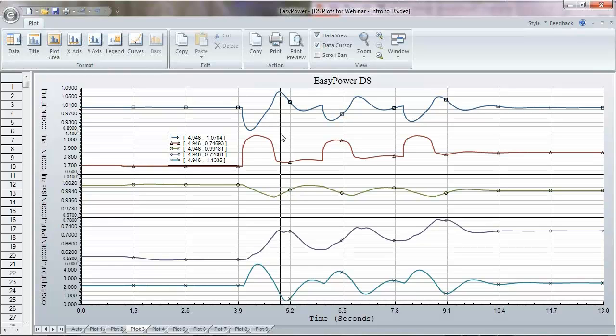Instead of putting it on a drive and controlling its flow, it's on a start. They have it start, then stop, then start, then stop. And I saw that happen repeatedly up there on the bridge. But this was affecting every power outlet, everything on the whole ship. So this is a response that's seen a lot for isolated cogeneration or just isolated generation, and how it responds to a motor start condition.